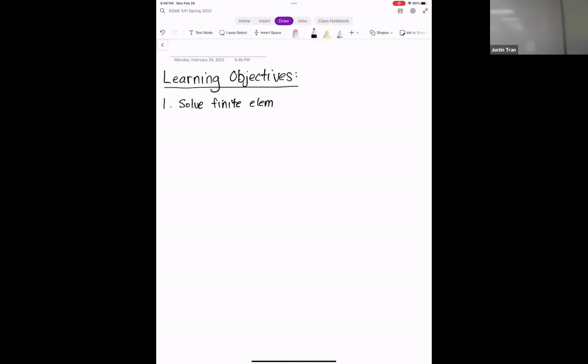Okay, and then this is pinned, so F2y is 0, but you have a moment, right? Yes, correct. And over here you have both. Yes. And the overlap of your global matrix is at U2y and theta 2, and U3y and theta 3. There should be no overlap on 3 because there's only one element.